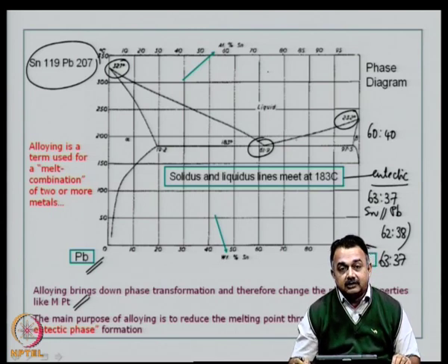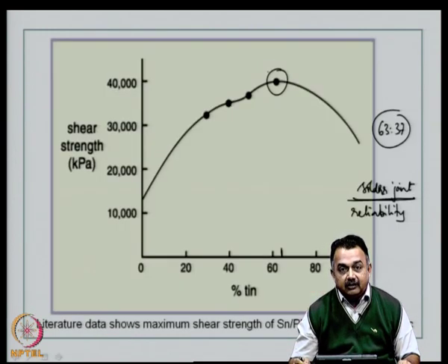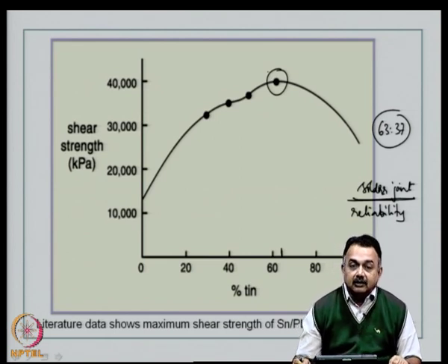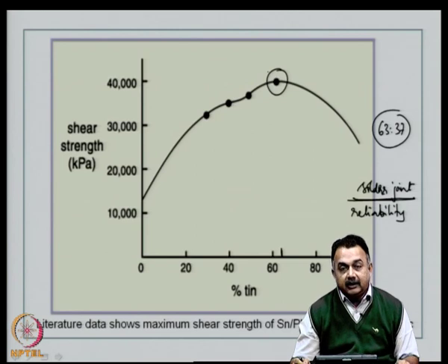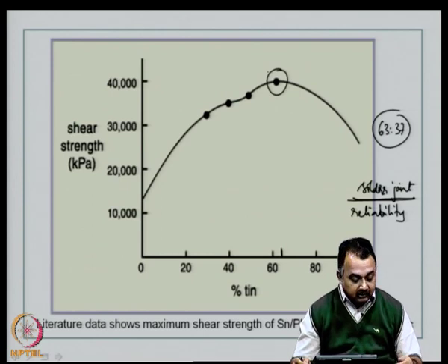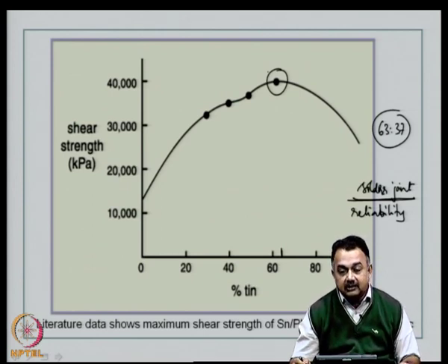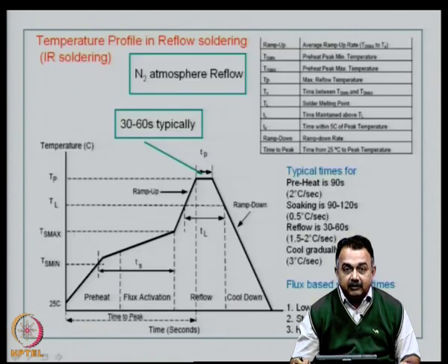This is very important because you are going to understand the effect of melting point, the solder paste melting point, and the substrate Tg. All three are very important in deciding the thermal profile of your reflow process or your wave soldering process. Typically thermal profiles are very important for doing a reflow process. In a wave, obviously you are using molten solder for through hole components and a few SMD devices. So, this lecture we will focus on reflow process and the reflow thermal profile.